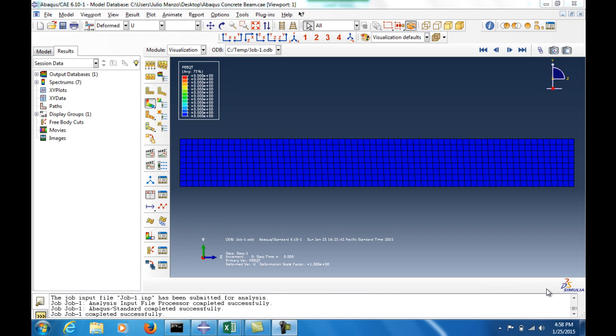Hi, this is the third video of a series of videos on how to model a reinforced concrete beam in Abaqus. Before we start anything, in the previous video I meshed the part with a size of 0.25 inches, a quarter inch. That ended up being too small, and it will take about 6 hours to complete the analysis on a quarter of a beam, a quarter of the model.